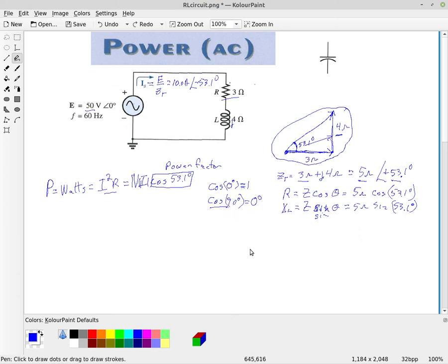All right, so if we just had our simple voltage source here and it was feeding an inductor with no resistance at all, we would still have current flow. But remember what happens here: this current charges up energy. It puts energy into the inductor during half the cycle, and then the other half of the cycle, it dumps that energy back out.